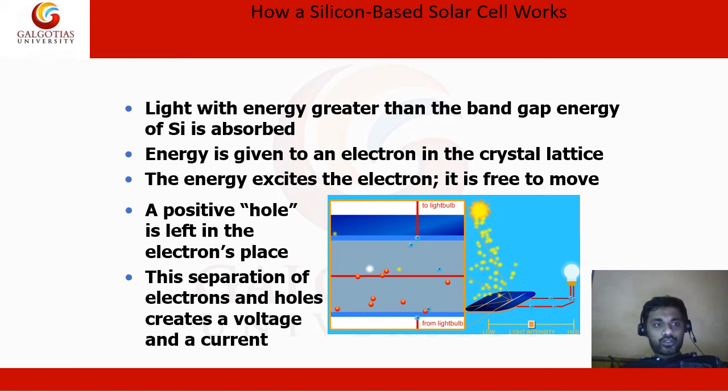Now coming to the working principle of a solar cell. When light reaches the p-n junction diode, the light photons can easily enter the junction through the very thin p-type layer. This light energy in the form of photons will supply sufficient energy to the junction to create a number of electron hole pairs. The incident light will then break the thermal equilibrium condition of the junction, and the free electrons in the depletion region will quickly come to the n side of the junction, and similarly the holes in the depletion region will quickly come to the p-type side of the junction.